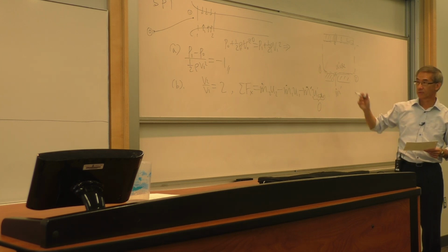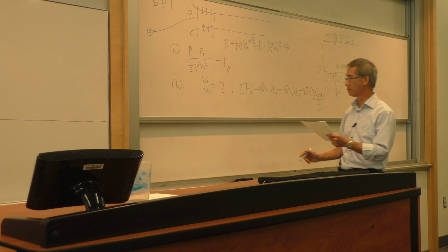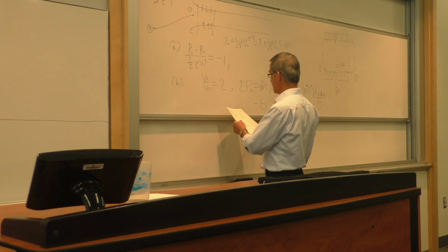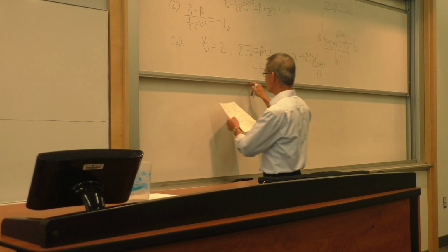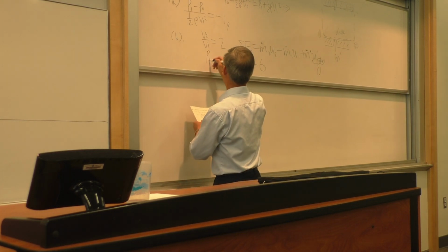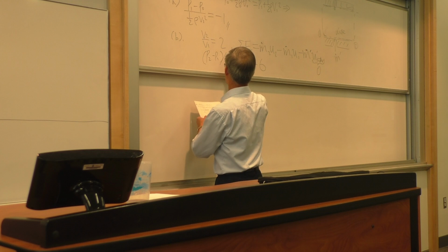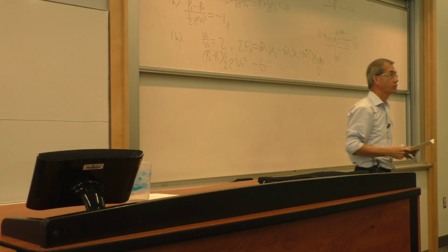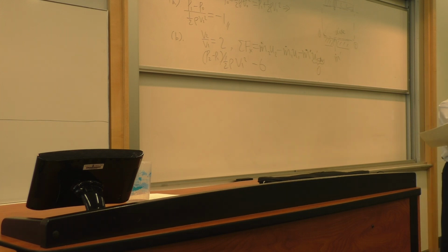But the answer, when you couple continuity with this momentum, is the pressure coefficient is -6, in the form of P2 minus P1 normalized by half rho V1 squared. So let me stop. This is perhaps the tricky part of the problem.